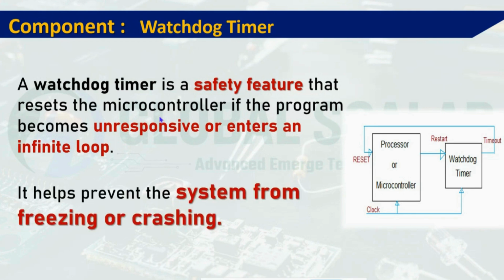It helps to prevent the system from freezing or crashing in real-time conditions. So this watchdog timer is a safety feature. It always resets the microcontroller if the software gets stuck in an infinite loop or malfunctions, where it ensures that the system remains responsive all the time. So the system should get a response whenever it gets stuck in any part of the unit.